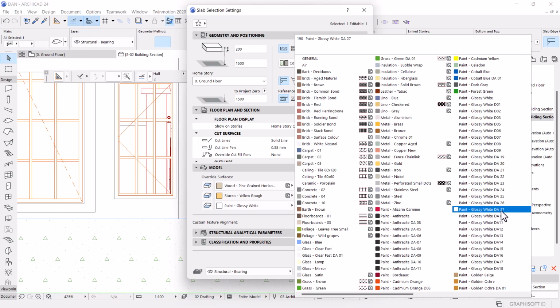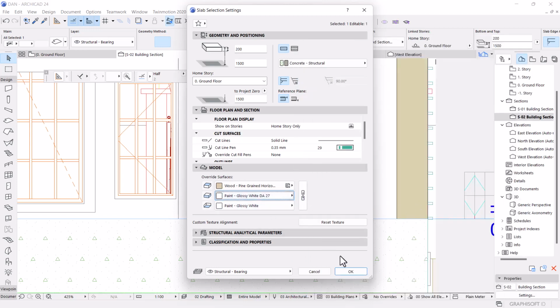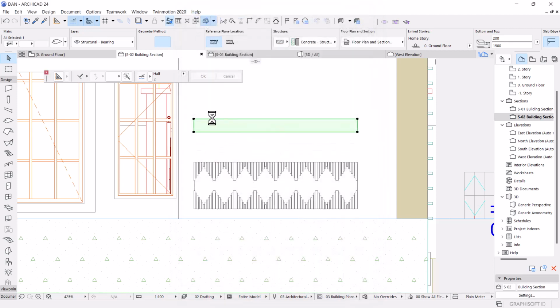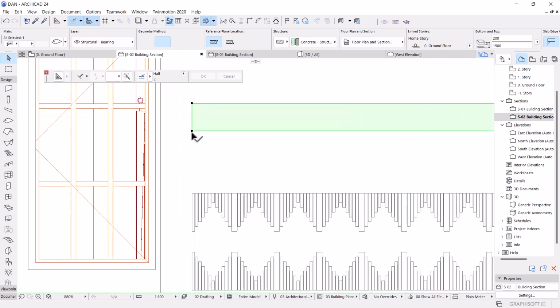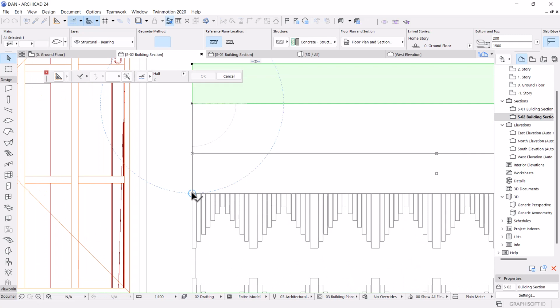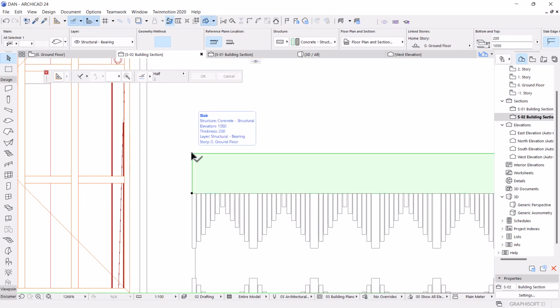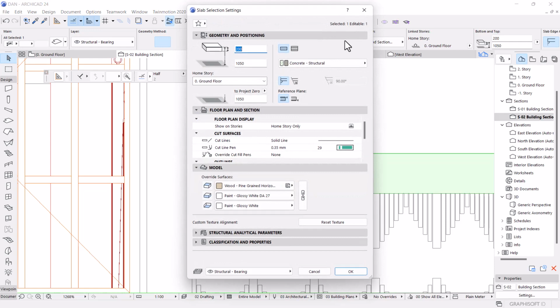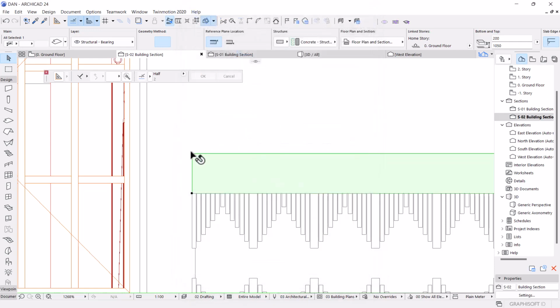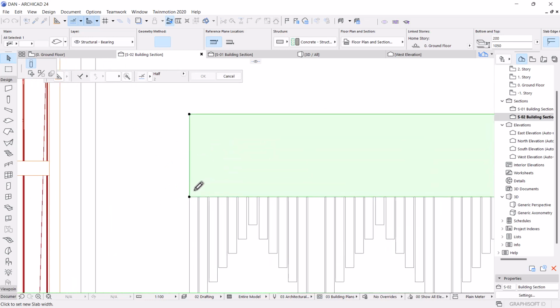For now you can change other parts later. Click OK. Then I'm going to drop it, Ctrl D, to that point, and now I can adjust the thickness. You can do it from here or from here, but basically I want it to be, you can do 25.